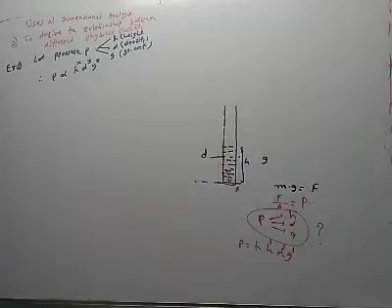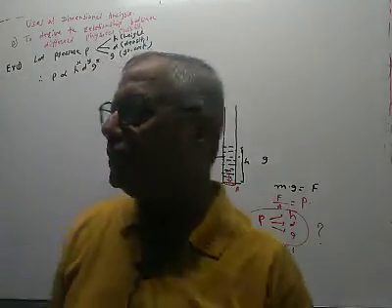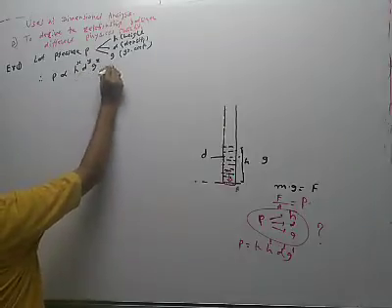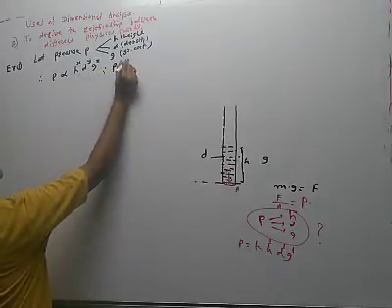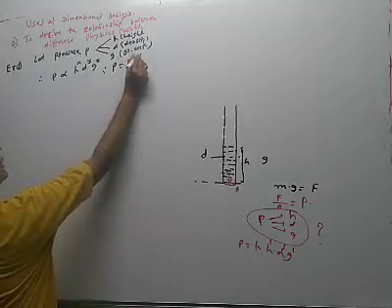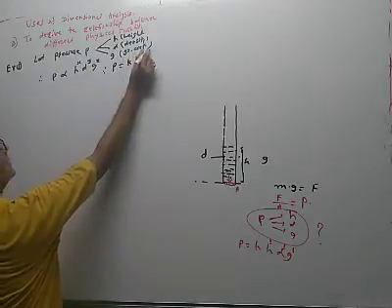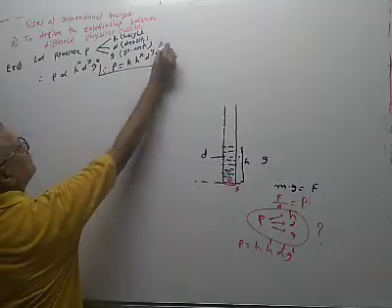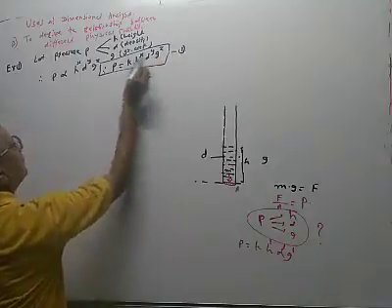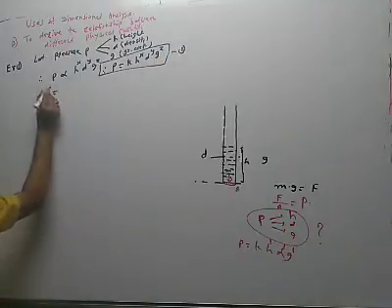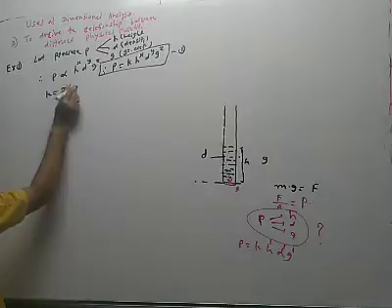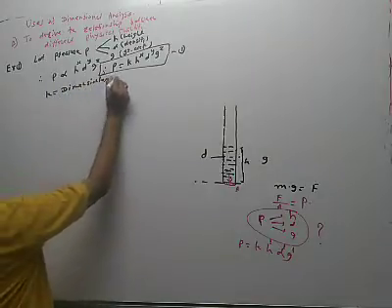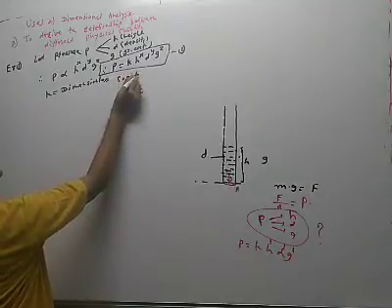Now, in science, particularly in math and physics, we know that when we remove the proportionality sign, we have to take some constant, and therefore the pressure P is equal to some constant of proportionality K into H raised to X, density raised to Y, and gravitational acceleration raised to Z. So this is equation 1, where K is a dimensionless constant of proportionality, it has no dimensions.